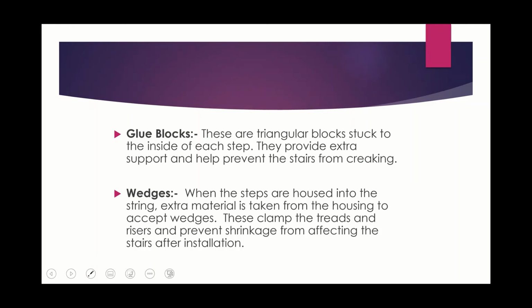Now, moving forward, glue blocks and wedges. These are there essentially to improve on the stability of the stairs. Glue blocks, these are triangular blocks stuck to the inside of each step. They provide extra support and help prevent the stairs from creaking.